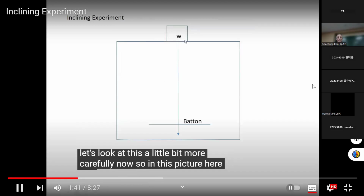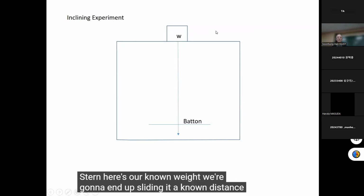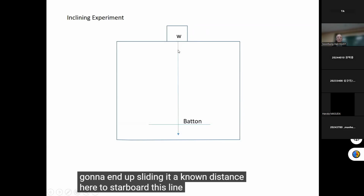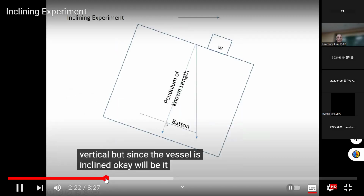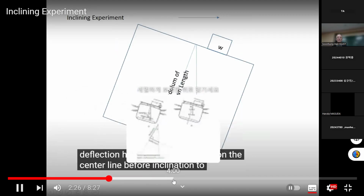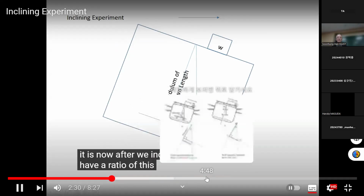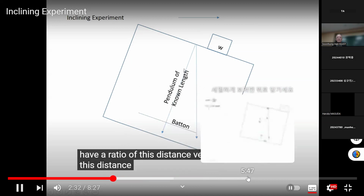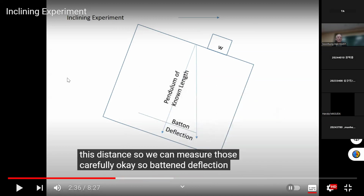In this picture, this is our vessel. We're looking at it from astern. Here's our known weight. We're going to slide it a known distance here to starboard. This line here is our pendulum, and our pendulum is lined up on the center line. We'll have this deflection from where it was on the center line before inclination to where it is now after we inclined it. So we have a ratio of this distance versus this distance, and we can measure those carefully. So, batten deflection.